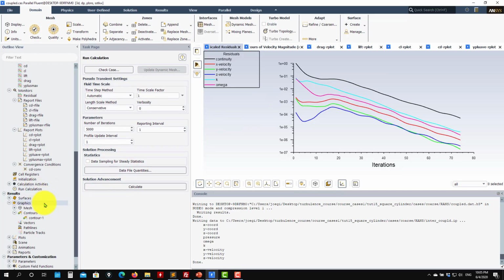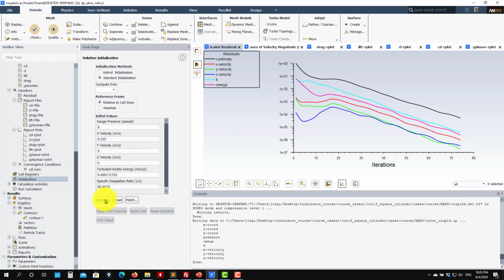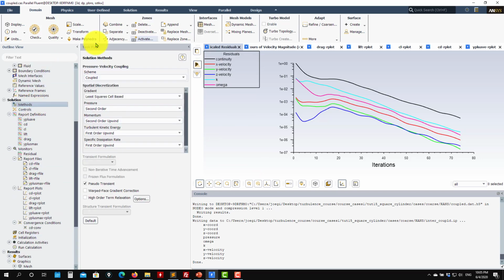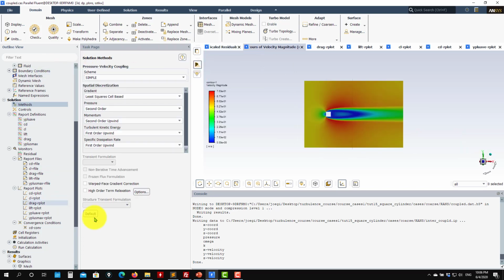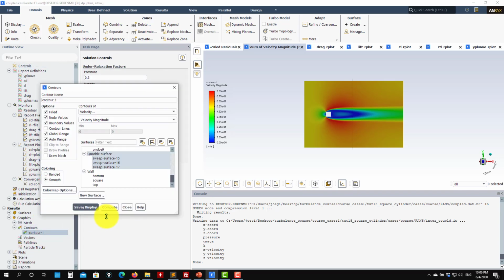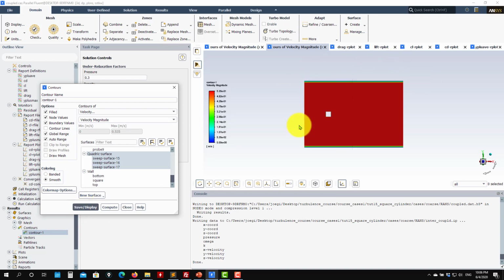So now let's do something. Let's again initialize, zero initialization, and the only modification that we are going to do is just changing the solver. Okay, so recall that this one is converging in like 70 iterations, very fast, and let's go to the simple solver. Okay, this is the other family, these are the segregated solvers. So, let's use the default parameters. Okay, so you go here, everything is alive.